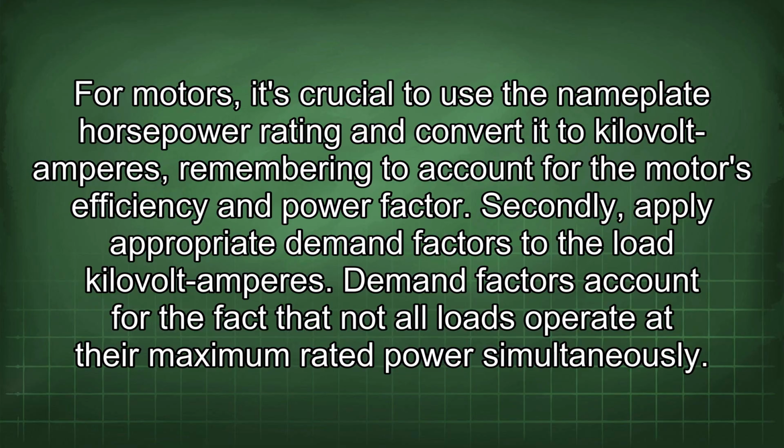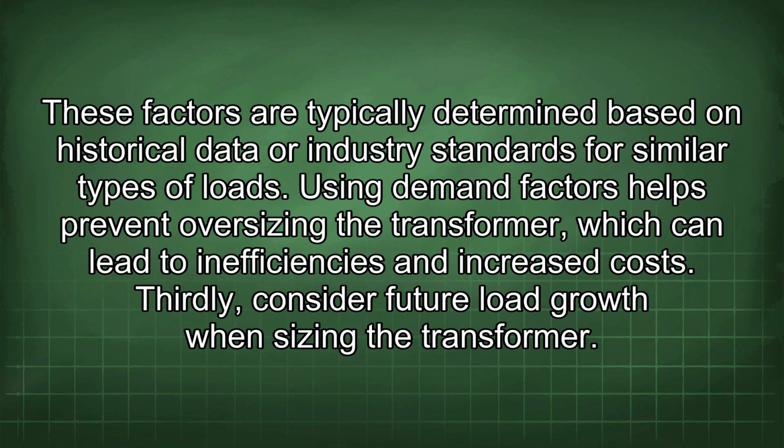Secondly, apply appropriate demand factors to the load kilovolt amperes. Demand factors account for the fact that not all loads operate at their maximum rated power simultaneously. These factors are typically determined based on historical data or industry standards for similar types of loads. Using demand factors helps prevent oversizing the transformer, which can lead to inefficiencies and increased costs.